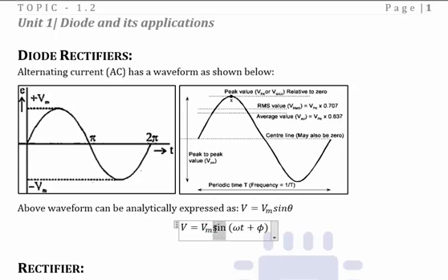The sine shows the nature of the signal, because the nature is sinusoidal. And in the bracket term we have omega. It expresses the frequency. Actually we can express omega as 2 pi f, so this f is the frequency of this signal. We can measure the signal from 0 to 2 pi, this complete cycle of signal, and the time required to complete the cycle is known as the time period of the signal.